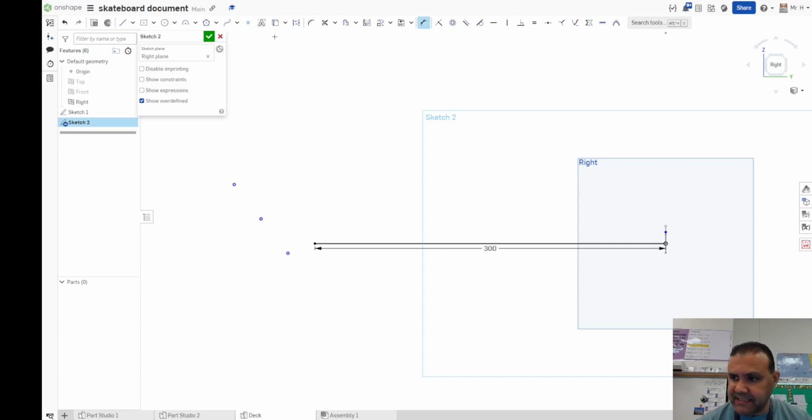So again, hit D for dimension here, and I'm going to dimension this one first. I'm going to want to lock it in place, and I'm going to do it at a dimension of the distance from that point of 38.07 millimeters, and then a height, putting to the left there, of 4.183 millimeters.